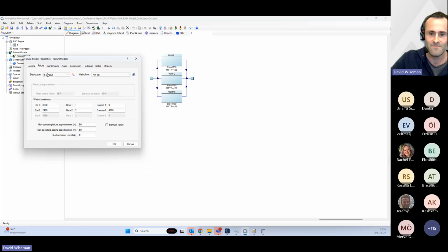So in there, instead of using an exponential distribution, which would give me a mean time to failure, I'm using, in this case, a bi-Weibull. The bi-Weibull is actually two distributions, essentially two Weibull distributions stacked on top of each other. Again, I don't want to give you a statistics lecture because I probably couldn't, but I will say, like I said, a Weibull distribution is used to describe different failure rate behaviors.